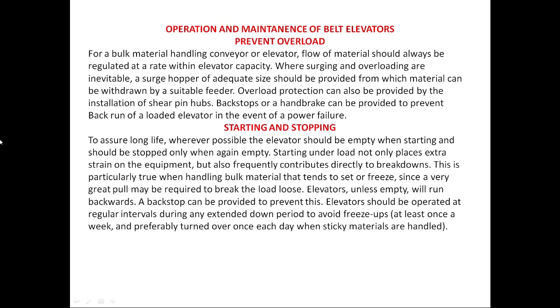Starting and stopping. To assure long life, wherever possible, the elevator should be empty when starting and should be stopped only when again empty. Starting under load not only places extra strain on the equipment but also frequently contributes directly to breakdowns. This is particularly true when handling bulk material that tends to settle or freeze, since a very great pull may be required to break the load loose.